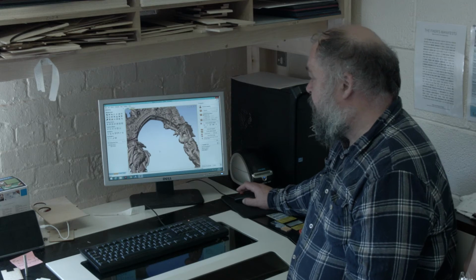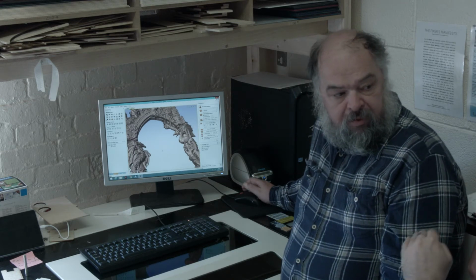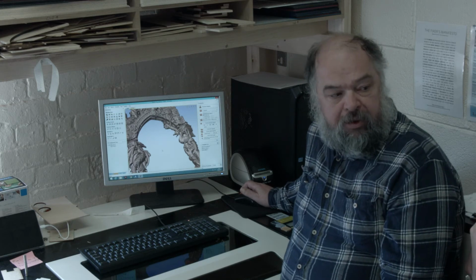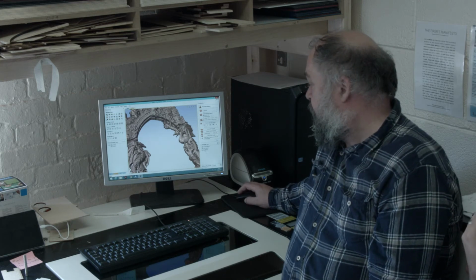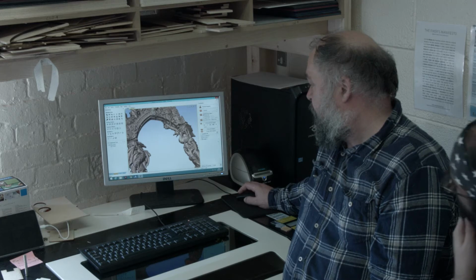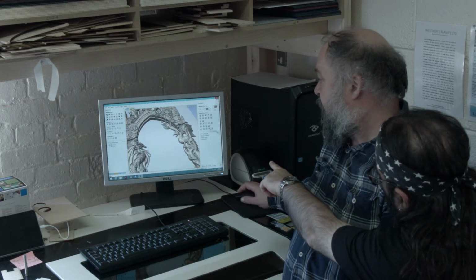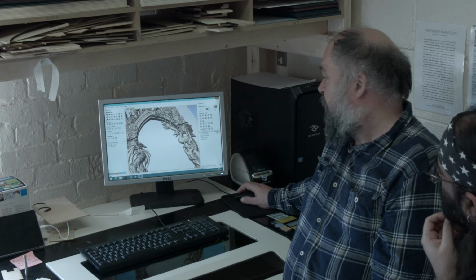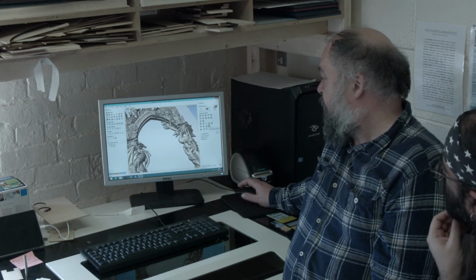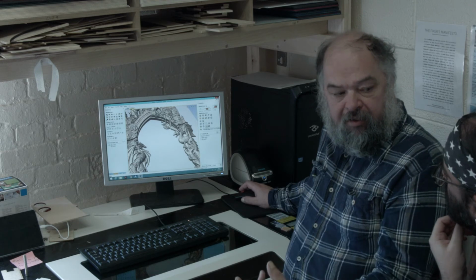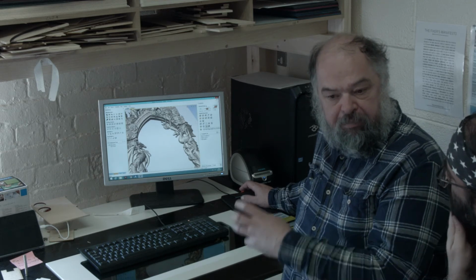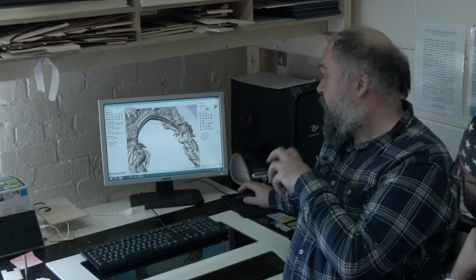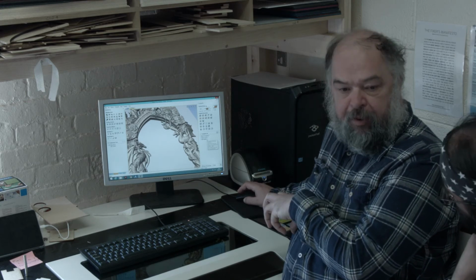And you were doing the roughing and then the finer. Are you piling up G code? Effectively, yeah. What it's doing is if you go into here, you've got the save for the G code on here, so you can save the tool path. You can save the G code out, and then that allows you to go in from there. So it'll have a G code for the roughing path. It'll have a G code for the finish path, and a G code for the profile.